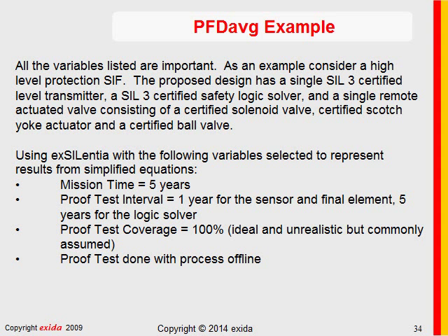I've seen many situations where there was a shutdown, there was a good set of proof testing done during the shutdown, but there was no major overhaul. So a mission time is the amount of time you run a process before shutdown and major overhaul, so that all the safety function equipment is replaced or rebuilt as new.